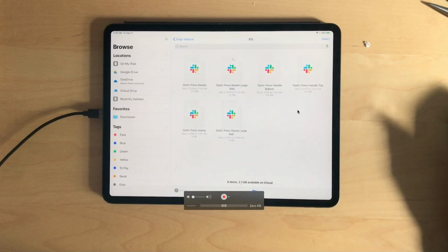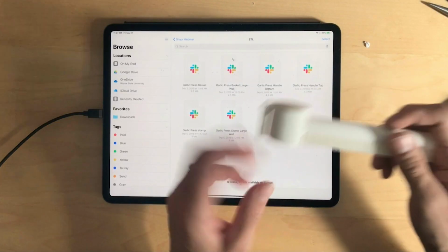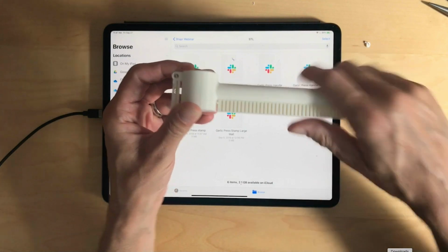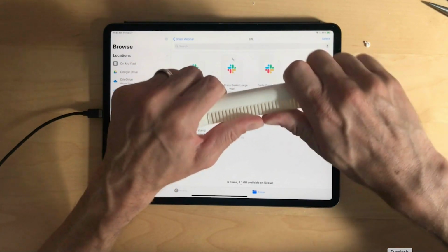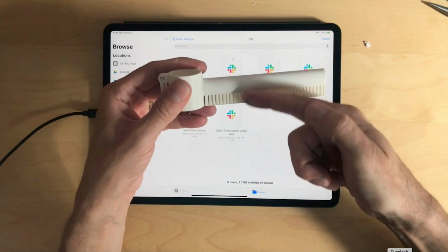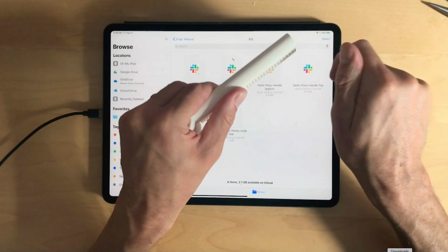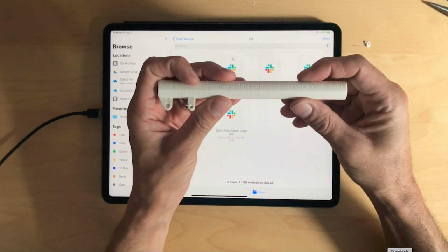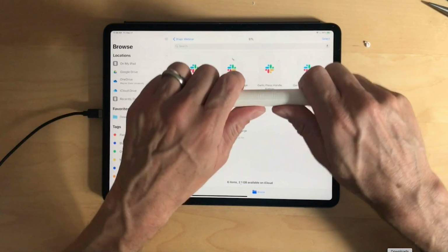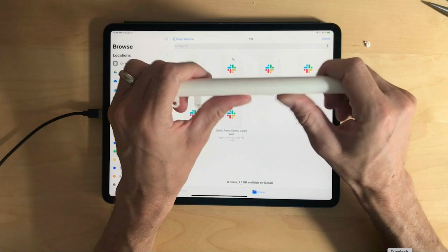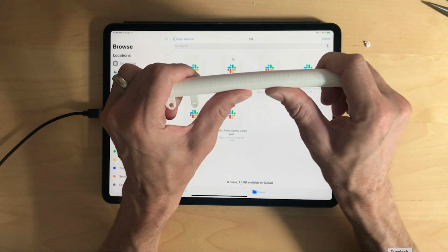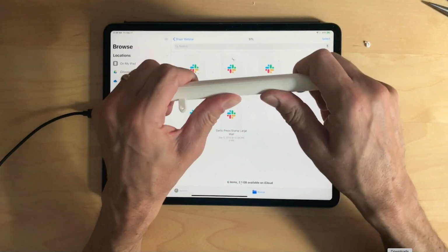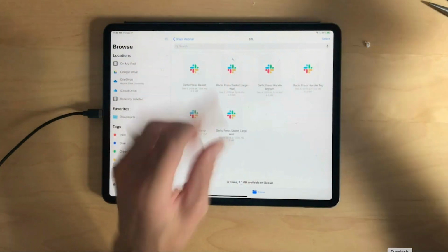Now I'm switching back to my camera for the moment, and here you can see that these layers are horizontal. So when I try to bend it this way, it's very stable. But in case these layers would be this way, I could probably easily, by accident, snap it. Here they're actually printed that way. If I take this, I mean, it's still a pretty good print. But you can see I can bend this a lot. This I can't actually bend as much. Okay.